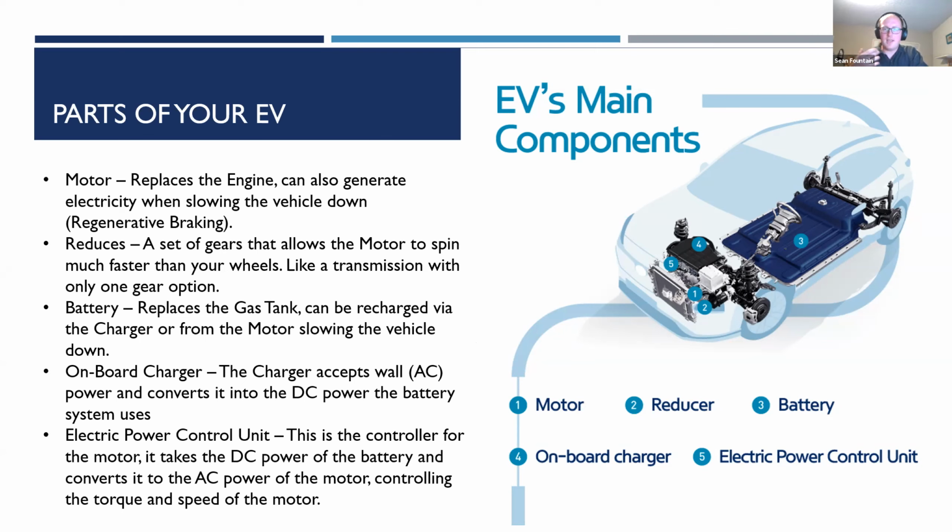Gasoline has a huge amount of chemical energy. I should have thrown in a specific number here to show you guys, but it's 5 to 10 times the range per volume and weight versus a lithium battery. And that's even after the gasoline engine turns most of that into heat.